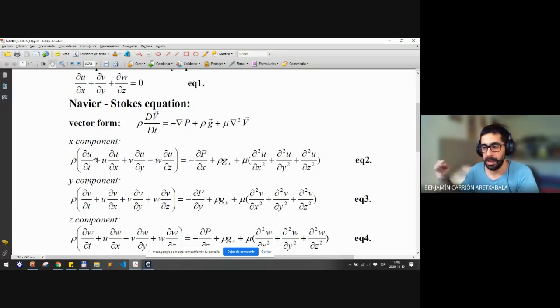So as a particle moves, the velocity is changing, and therefore it feels acceleration, even though we have steady state, right? So the velocity is not changing over time, but as you move through the velocity field, you feel that the velocity is changing, and that's by definition acceleration. We call this convective or advective acceleration, right?